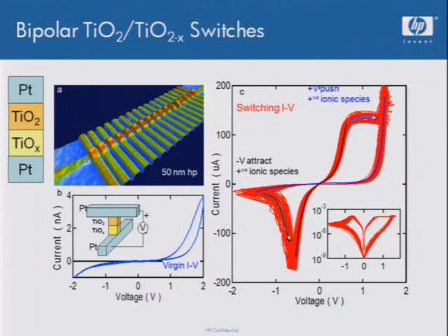And so we had two layers of titanium dioxide in the devices, and what we could see by running current voltage characteristics is this type of pinched hysteresis loop here. And for this particular sample, it turns out that the interfaces were fairly clean. And so one of the interfaces here is a metal semiconductor interface. So we have a Schottky barrier there, and you can see the Schottky barrier right here in this part of the IV curve. What you see is that the off state, or the high resistance state of the device, is actually a diode, or at least a rectifying contact, a Schottky barrier. And then essentially what we do is we somehow turn that Schottky barrier into a fairly thin tunnel barrier.